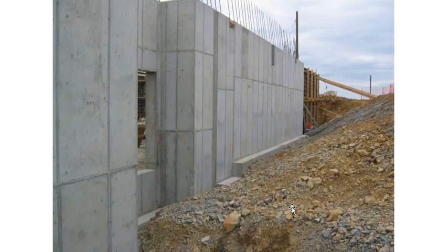Here, a nice looking foundation wall. Again, we see the vertical reinforcement, and here we see a ledge, often called a brick ledge. I don't know exactly what was to follow here, but something would rest on this. Often a brick veneer or a stone, or not a veneer, but an actual brick wall would rest there. Some type of a structure is being set up to live on that ledge.